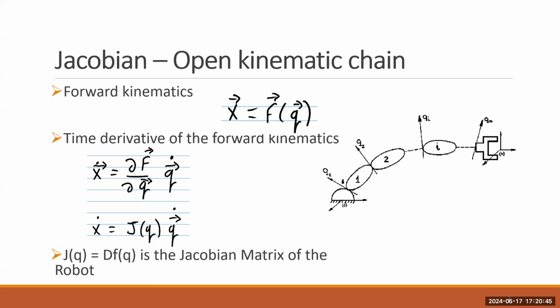So say we have a robotic arm, as you can see here, but not only a robotic arm. And we can say the forward kinematics is in terms of the configuration parameters of the arm, which are Q. Q are the configuration parameters, and F is a function of the configuration parameters, say the angles of the joints, and that maps the configuration parameters into the location and orientation.